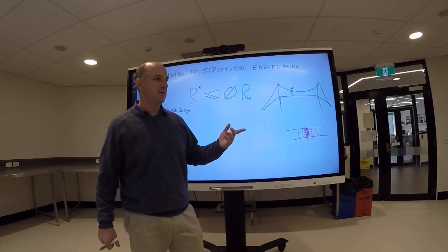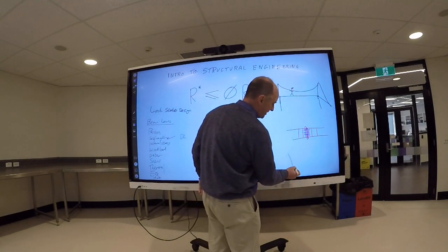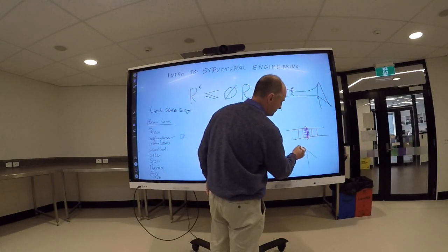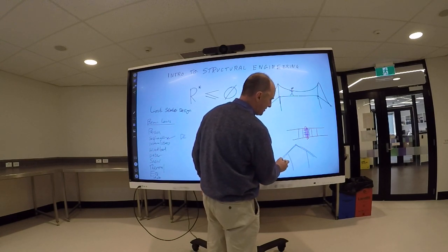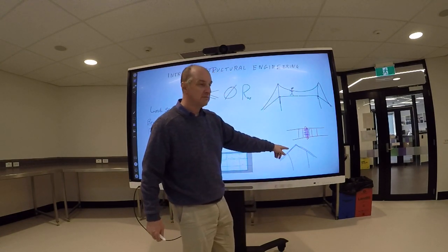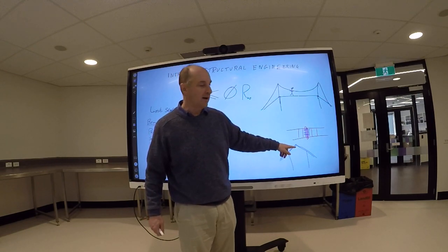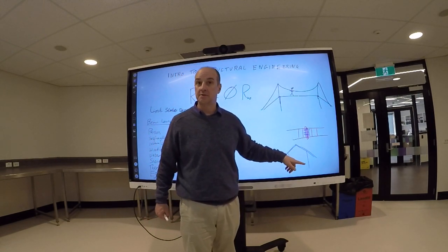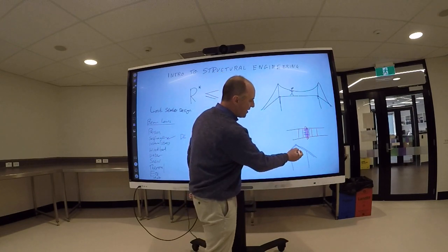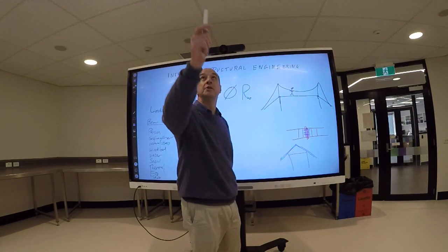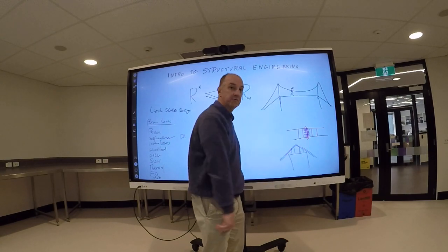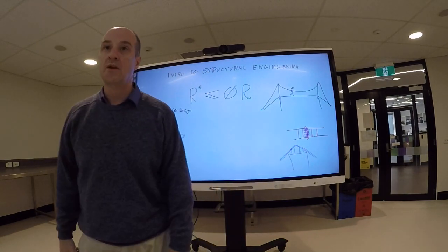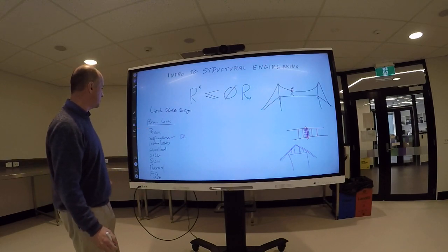Let's also talk about a house or a building that we're designing at the moment. If you're talking about the roof, the beams, the sheets on the roof, that's dead load. Okay. If you have a permanently installed ceiling like we do here, the ceiling's a dead load as well. There's the ceiling hanging off the roof. Okay. All right, then we go to live load.